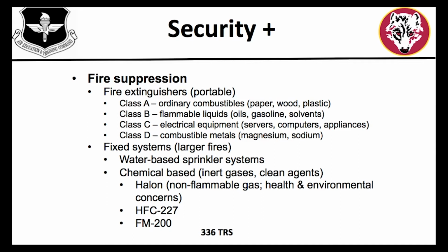Depending on environments, they'll look at that as maybe health concerns, environmental concerns. It's a non-flammable gas, but you usually have some better replacements, such as HFC 227, which is a part of FM 200. Those are clean agents. They extinguish the fires by suppressing and absorbing the heat. It's a combination of chemical and physical mechanisms. They're able to do this without affecting, on a large scale, the available oxygen in the air. It's colorless, odorless, and electrically non-conductive, unlike halon.